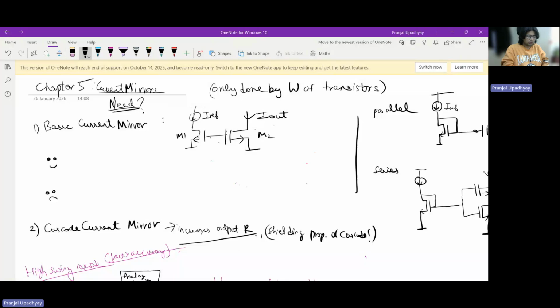So circuit designers have found one of the best approaches is to have a single bias current, which they call a golden reference, which is supposed to not change with process variations. Then they mirror it in different parts of the circuit, depending upon how much portion, fraction, or multiple of that reference current is needed.